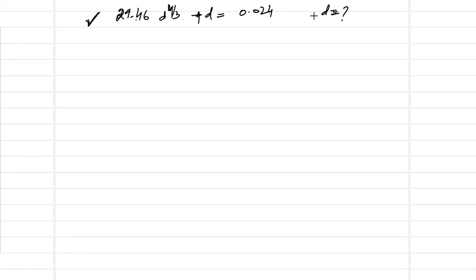But generally, I'll give you a hint: if you are unable to solve it from the calculator, you have a general idea that d, which is the wire diameter, of the springs that are made from these wires, varies from 1 to 10 millimeter. Generally, not in all cases. So in your exams, if you are able to solve this in your calculator directly, it's good. But if you're unable to, just use hit and trial. For example, let's start with the value of d equal to 3.